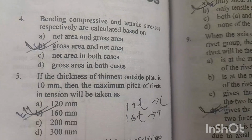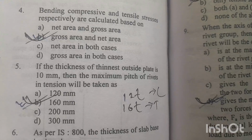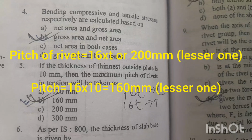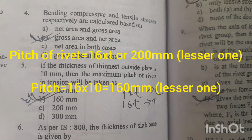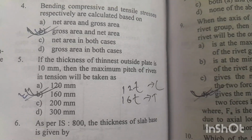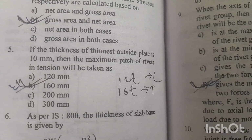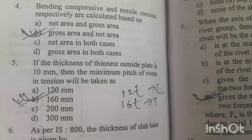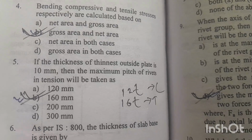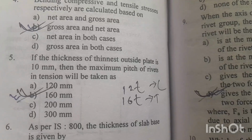Question number 5. If the thickness of thinnest outside plate is 10 mm, then the maximum pitch of rivets in tension will be taken as 16 T or 200 mm, whichever is less. So 16 into 10 equals 160 mm, which is less than 200 mm. So option B is right answer, 160 mm. But the pitch of the rivet in compression will be 12 T or 200 mm, whichever is less, where T is the thickness of the thinnest outside plate.